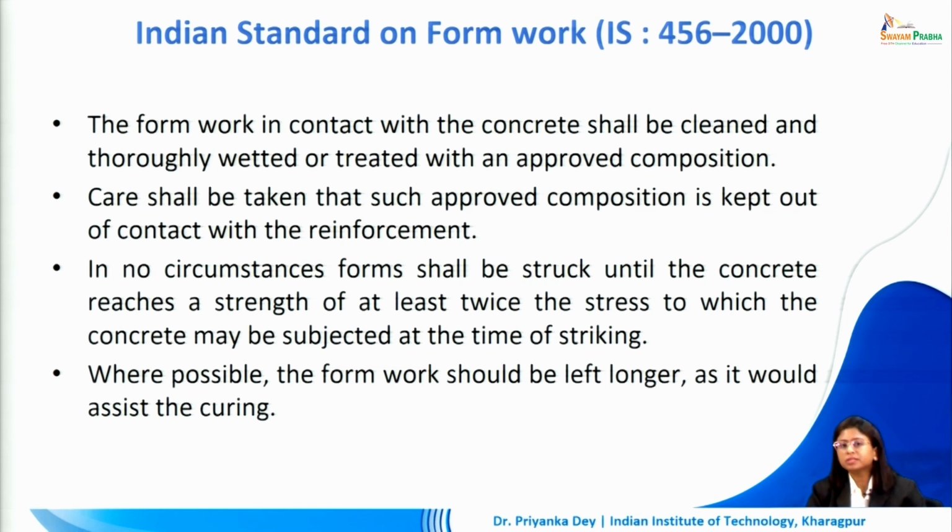In no circumstances shall forms be struck until the concrete reaches a strength of at least twice the stress to which the concrete may be subjected at the time of striking. Wherever possible, the formwork should be left longer as it actually helps in the process of curing of the concrete. So, one should not be in a hurry to remove the formwork as soon as they feel that the member being created has dried up or cured. Some time should be given.